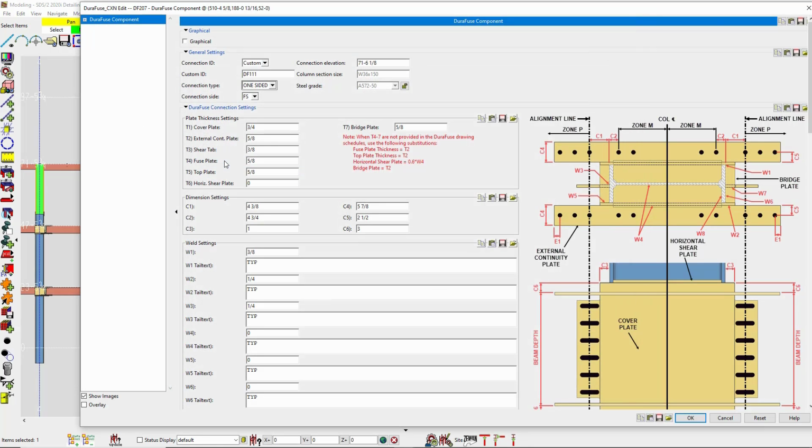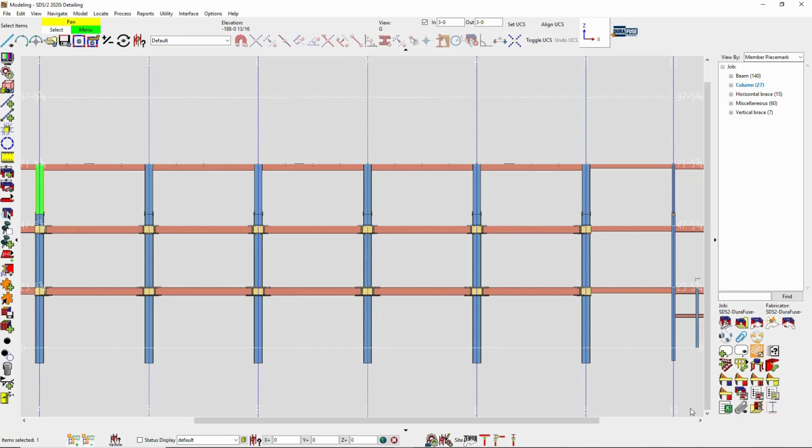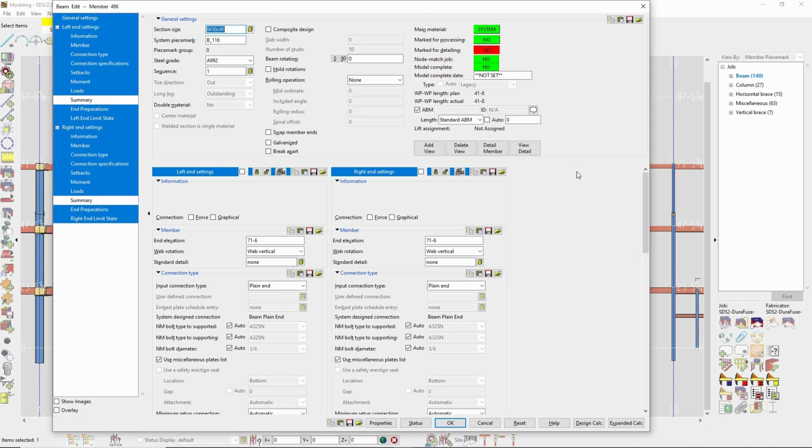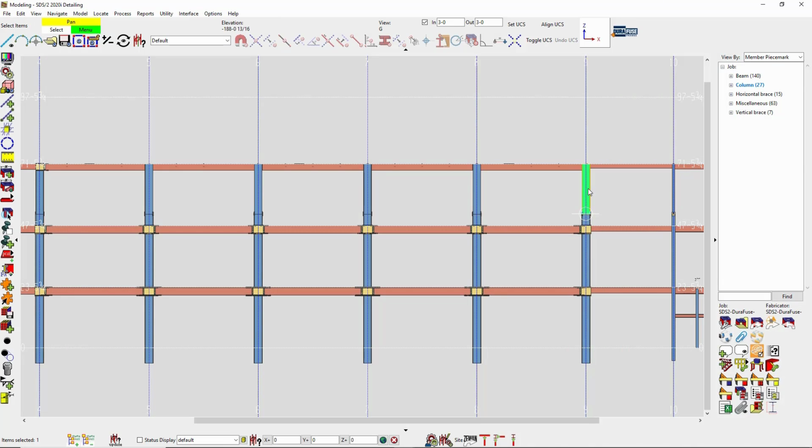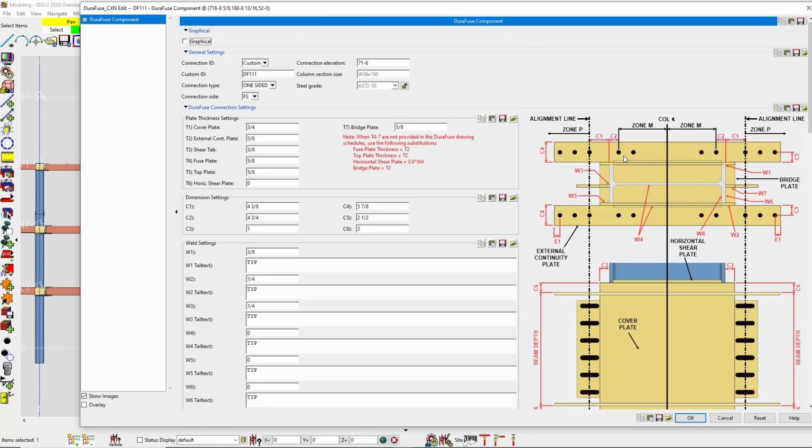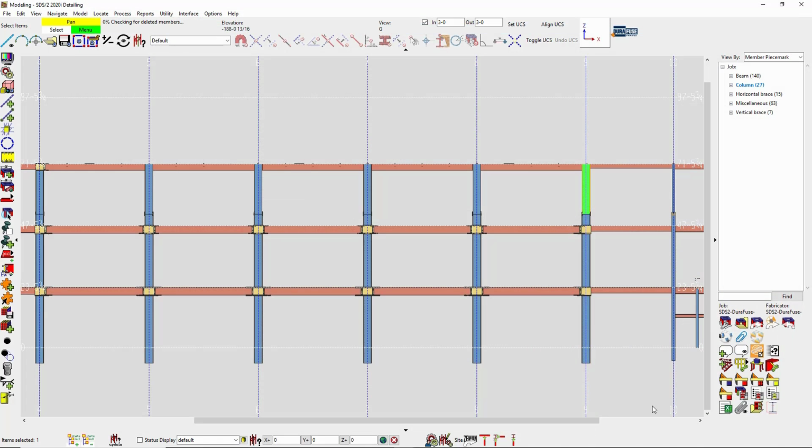Now we would reference our elevation view to see what connection we need to place. And when you fill out that form, it was bumping that up. So we just deleted the extra 1/8 there and it should apply our connection. Another way to get to that is to just click on the beam first to verify what connection elevation it needs to be and copy paste that in.